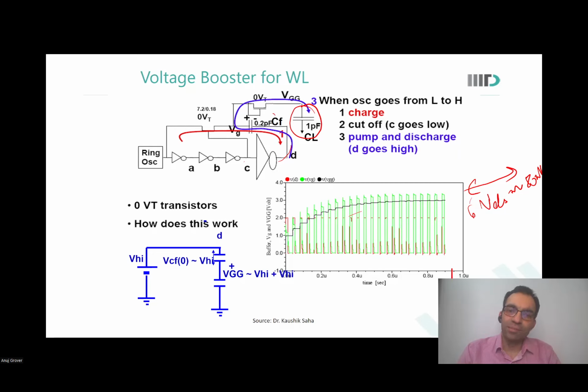But memory is giving output based on the output access time, right? Yeah. Memory could be giving output whenever. But when do you latch the memory output? That is what is important, no? Memory output will be latched somewhere, either in the next stage of flip-flop. At the system level also, you will need to latch the memory output, no? Somewhere. Yes, sir. So you do that after access time. Then there is no problem of whether there was junk before the access time or not. Is it clear?